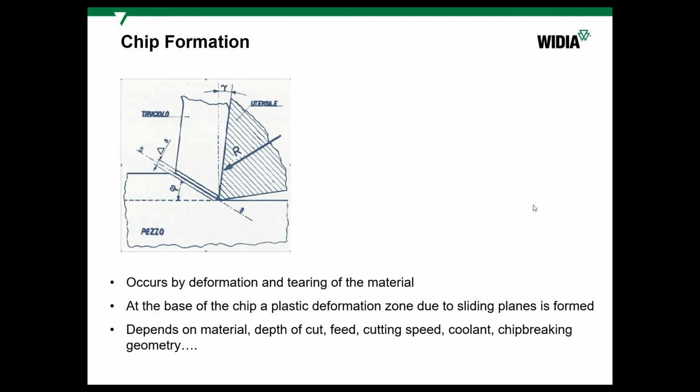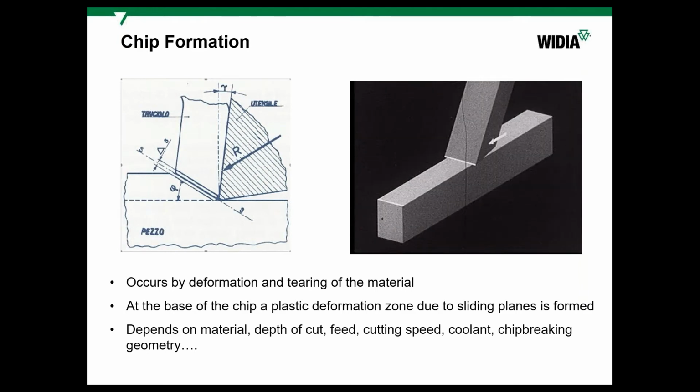The cutting process itself, if we look deeper, with magnification, for example on this example of turning, is based on the deformation of the metal when it's in contact with the cutting edge. Here is the rake surface, the clearance surface, and here is the area of chip deformation. We can play with that using different cutting data: feed, depth of cut, and also speed.